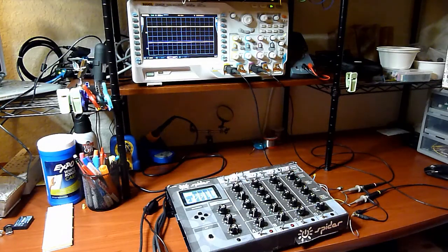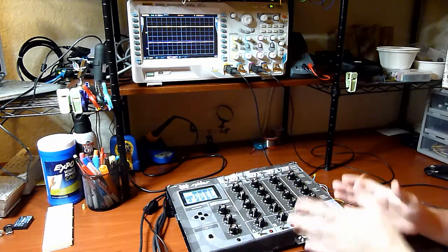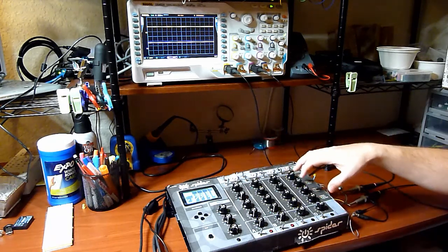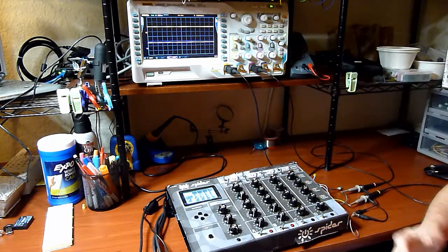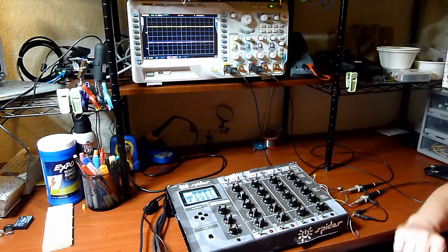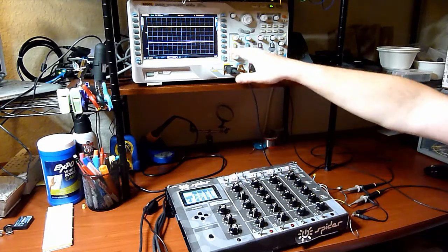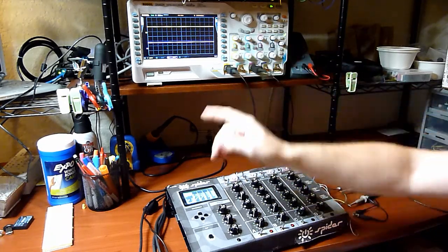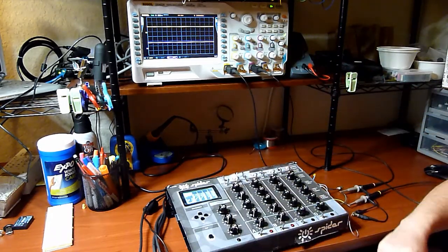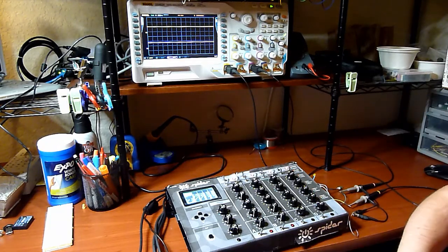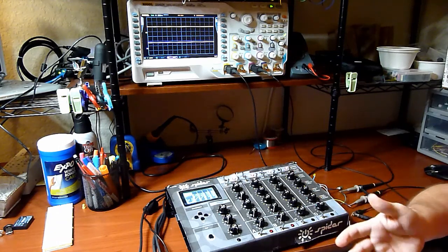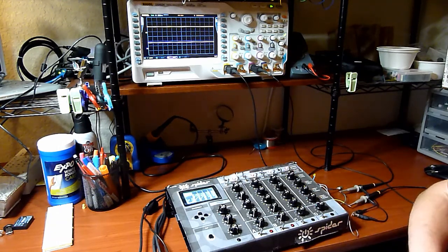Time for a little demo. Here I've plugged the spider onto my oscilloscope so we can see what's happening on the output. Channel 1 is yellow and channel 2 is purple, and yellow is plugged on the input of the synthesizer to control the pitch, and purple is controlling the ring modulator, the amount of mix between the filtered and non-filtered sound.